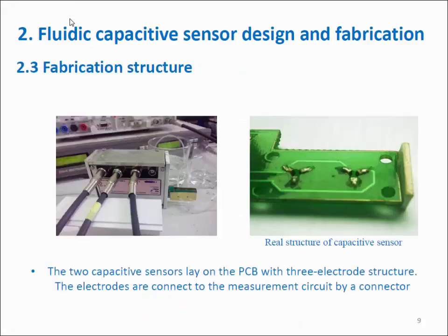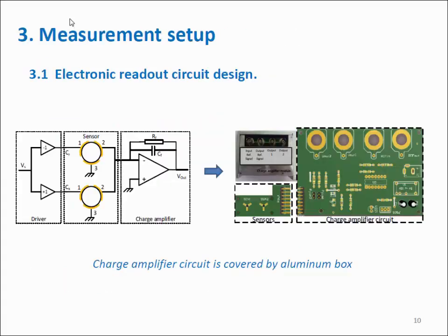And so we go into fabrication. You can see on this picture, this is the structure of 2 capacitive sensors. This is the copper and wire here, and here. And we have the reference channel, we have the sensing channel, and we make the system here. So in order to make the signal, we use the charge amplifiers, and we supply the signal of sine waves of 100 kilohertz.